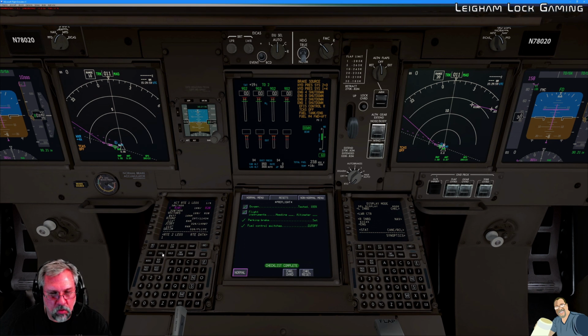We're going to put our left CDU onto takeoff reference. What's called for in the FCOM is that the first officer would actually bring up the legs control. I'm not going to do that, only because I want to maintain control over the ECAS display page, and I wouldn't be on legs very long if I set it at this point, so I skip that step.